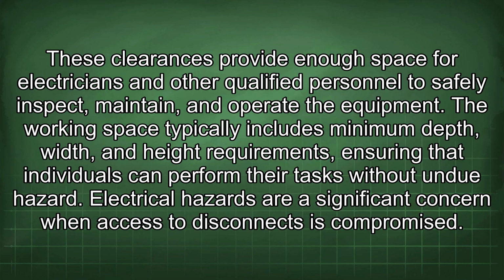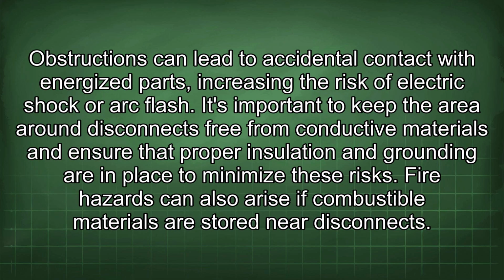The working space typically includes minimum depth, width, and height requirements, ensuring that individuals can perform their tasks without undue hazard. Electrical hazards are a significant concern when access to disconnects is compromised. Obstructions can lead to accidental contact with energized parts, increasing the risk of electric shock or arc flash. It's important to keep the area around disconnects free from conductive materials and ensure that proper insulation and grounding are in place to minimize these risks.